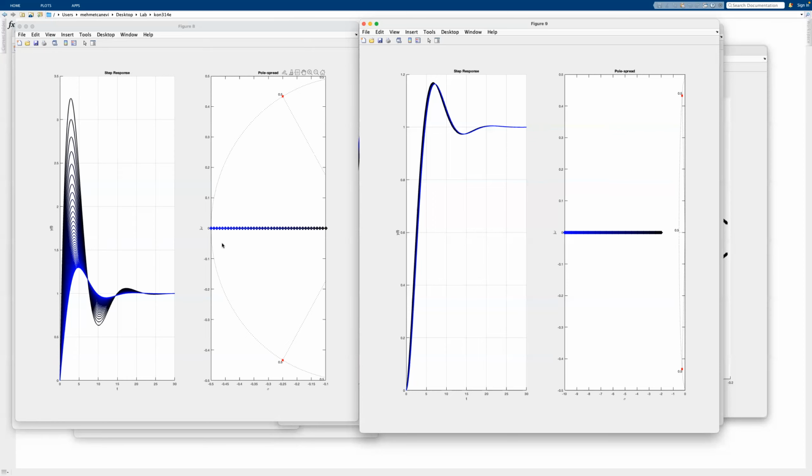But for most of the systems, you as the designer of the controller are going to be adding the 0 to the system, because if the system doesn't have a 0, the controller will have one. For example, if you're designing a PI controller, the PI controller has its 0, and you're the one deciding on the location of the 0. So if it's in the vicinity, that's going to be your fault.